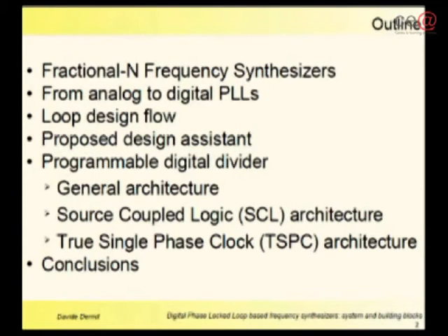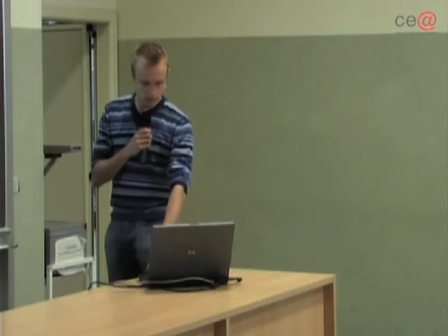Today I will show my research activity about frequency synthesizers based on digital phase-locked loops. This is the structure of the presentation. I'll begin the talk starting from an analog fractional-N frequency synthesizer, and then I will list the motivation that led several research groups in the past years to investigate the possibility of digital-intensive PLLs. Then I will describe the standard design flow and proceed to describe the design assistant that I propose in order to simplify this task. Concluding, I will show the blocks of the PLL that were realized at transistor level, as a conclusion of the work.